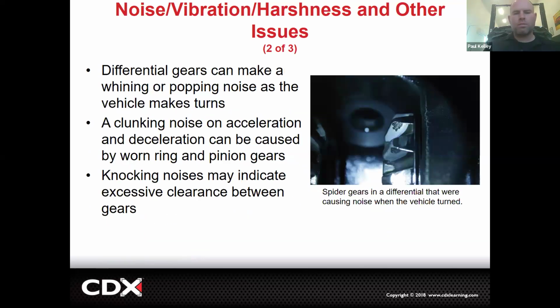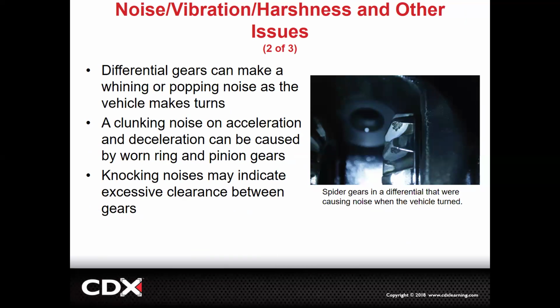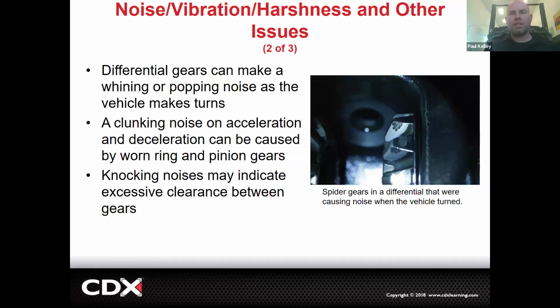Okay, but we're going to continue. So this, for example, is a spider gear defect. If this is a defect on the spider gear, when would you hear it? Anybody care to give a shot? On turns. Exactly. Bingo. So if ASE words it in a way where it's like going straight, it doesn't, but turning it does, you might be thinking damage on the spider gears, on the side gears or differential pinion gears. Cool.